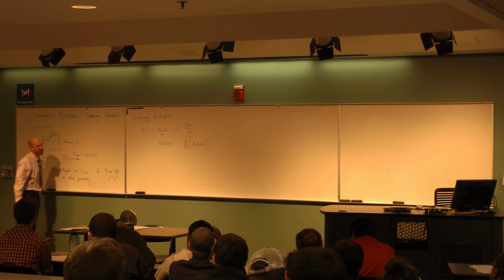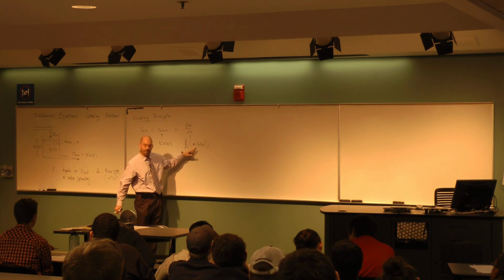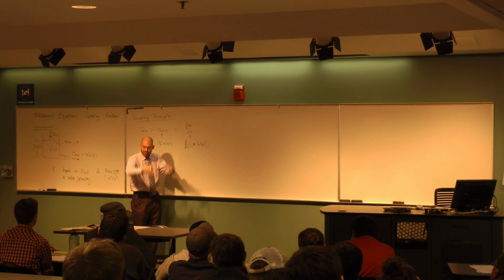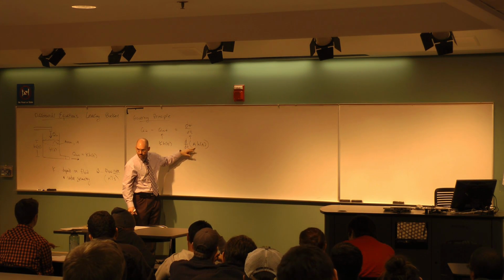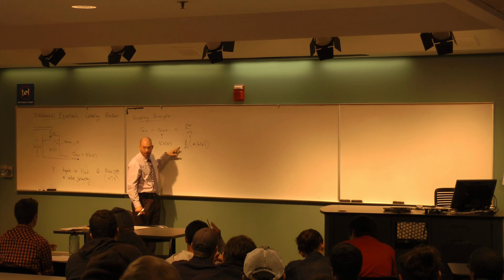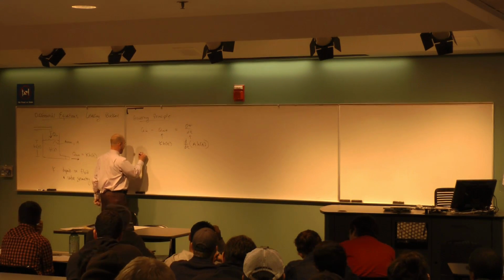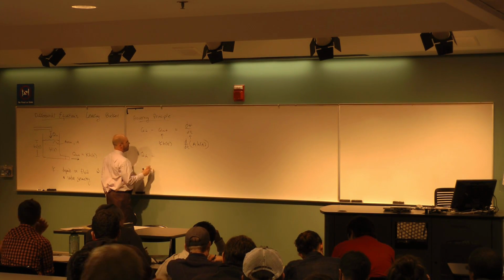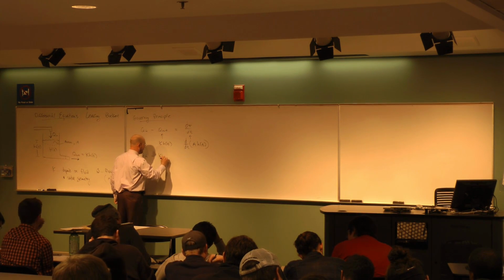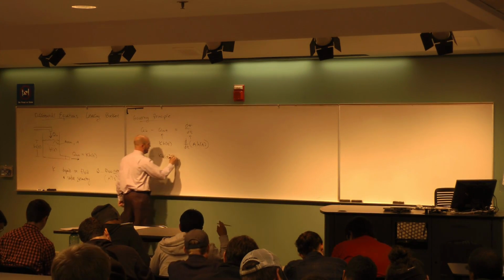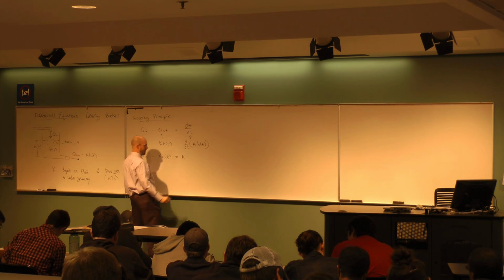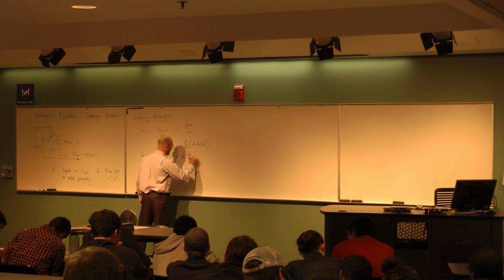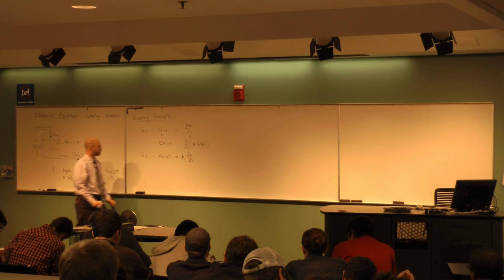Okay, but so for the purpose of this, let's say it's prismatic, right? All the cross sections are the same, no matter what the shape. Then the area happens, what do I do with this? I can pull it out front, right? So now we've reached this point, Q in minus Q out, which is K h of t, is equal to this derivative. The A can come out front, and then I'm going to have this derivative dh dt.